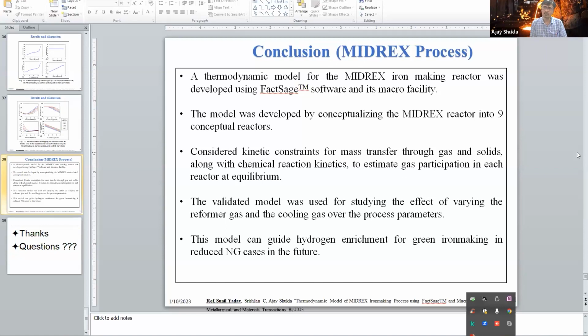And if we have gangue mineral in the iron ore as well, it is also going to multiply the problem and increase the slag volumes further. And it will also require more coal because of the oxide material which is required to be melted. So definitely, you're right that there also the slag volumes are going to be more if you use iron ore with high gangue mineral content.